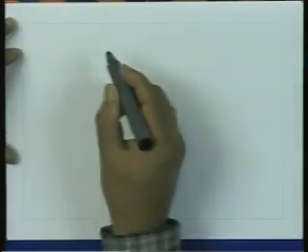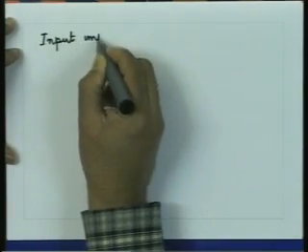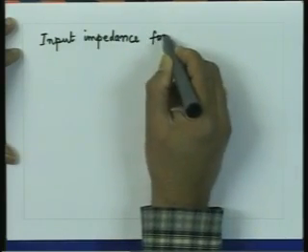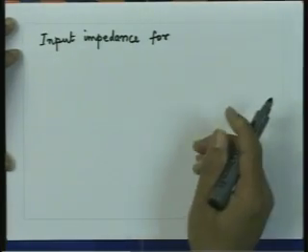In general, since we are considering loss now, the input impedance of the open or short circuited line has to be written in the total propagation constant gamma and not only the phase constant. So, if you go back to your original impedance relationship which we have derived and substitute ZL equal to either 0 or infinity depending upon whether a short circuit or open circuit, I get the input impedance. So, this is the input impedance for a line of length L when the line has a loss.